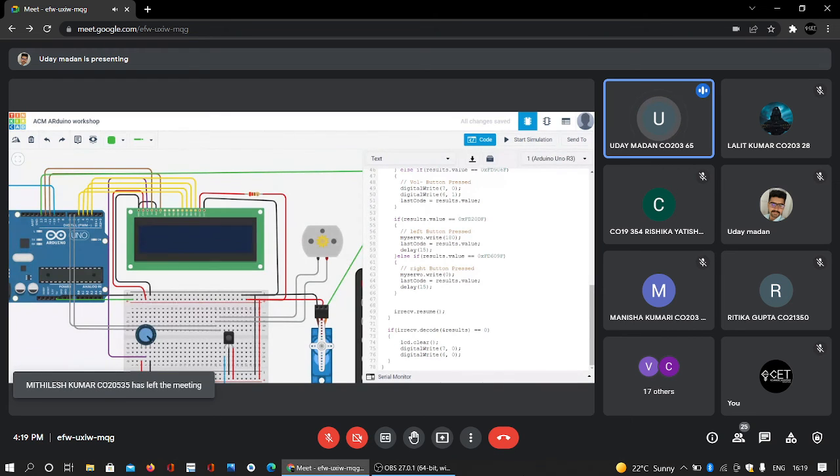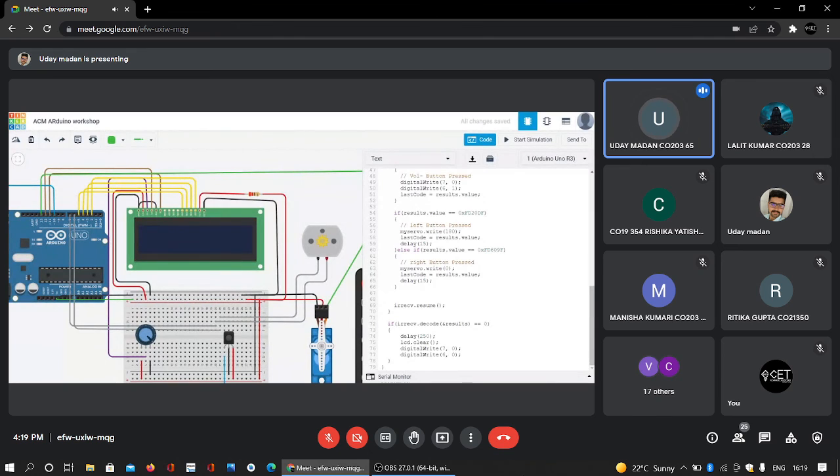Okay, so digital after digital writing, we need a delay here. If there is no signal, wait for signal for 250 milliseconds. If no signal comes under 250 milliseconds then execute this. So we are giving a delay of 250 seconds here, milliseconds, sorry. Seconds is very large, so we are giving a delay of 250 milliseconds here.